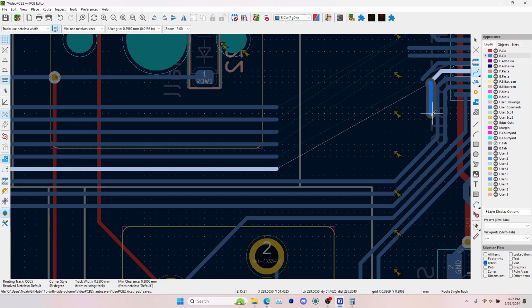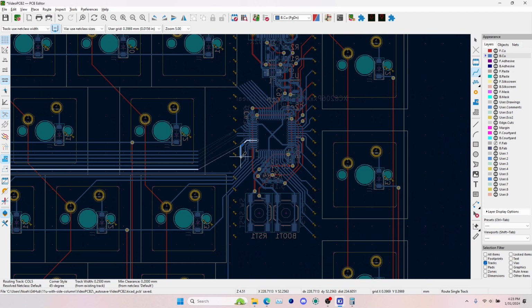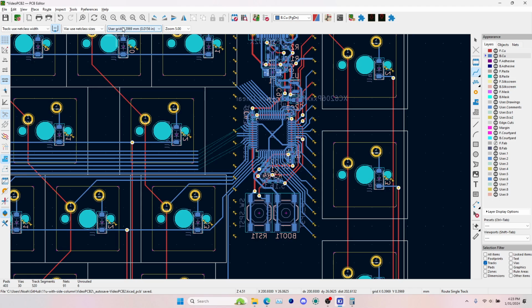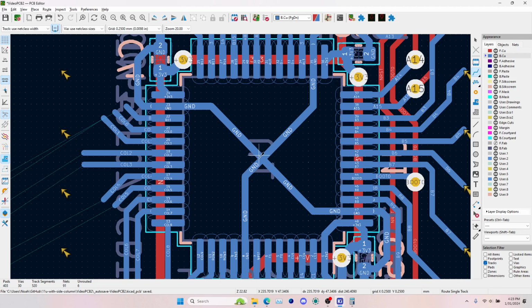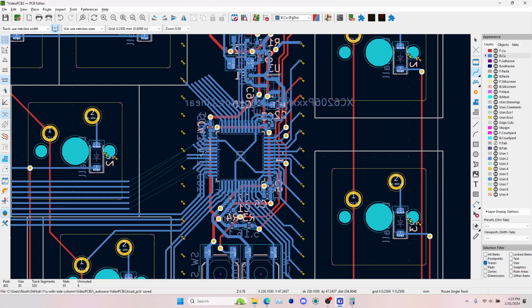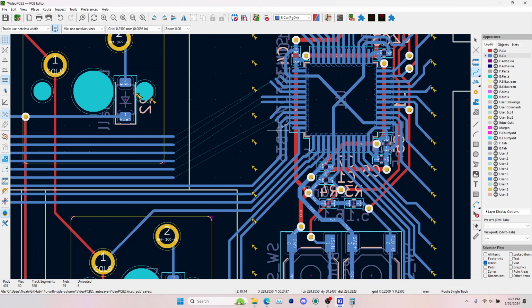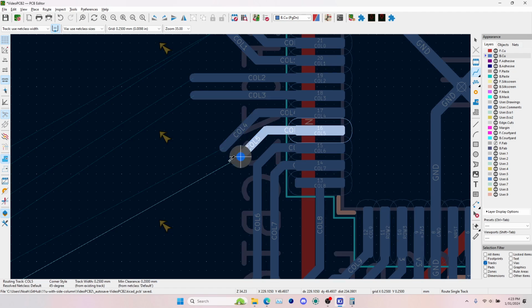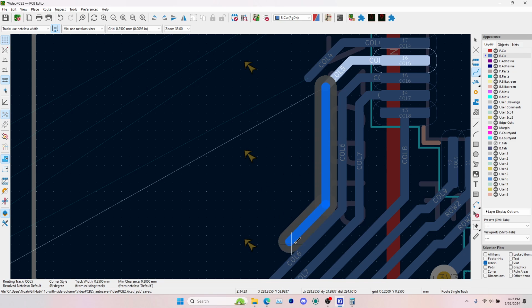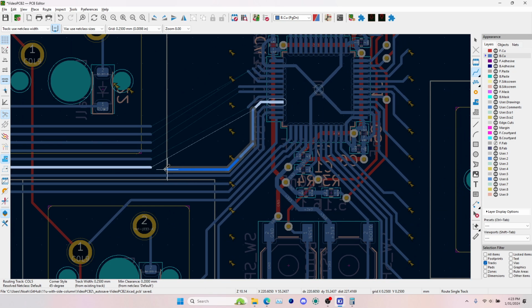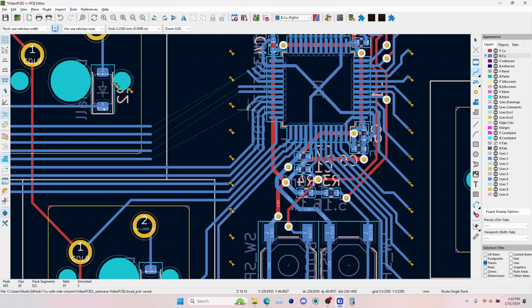And I like the way these kind of come out sideways, so we'll continue that pattern just by changing our grid to 0.25 millimeters and making our grid origin the center of the chip. Right? So we place the center of the chip on both grids. 2.5 millimeters is the grid that this project, the template, was made in. So we can continue the nice even spacing.